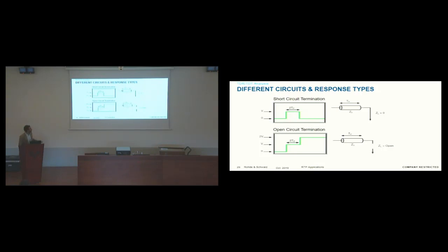And by calculating the time difference between these steps, we can calculate not only the time between these mismatches, but also the distance, if we know some parameters of our PCB, like the electric permittivity of the material.